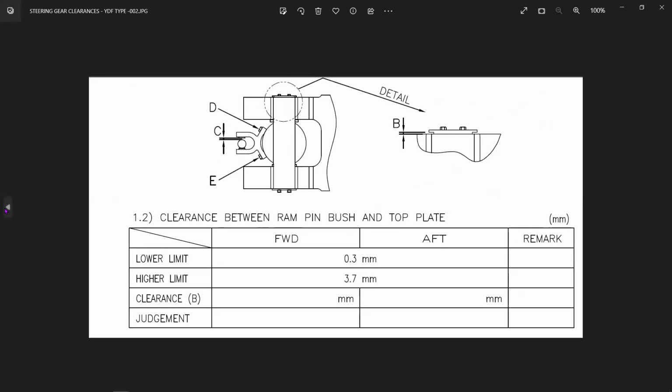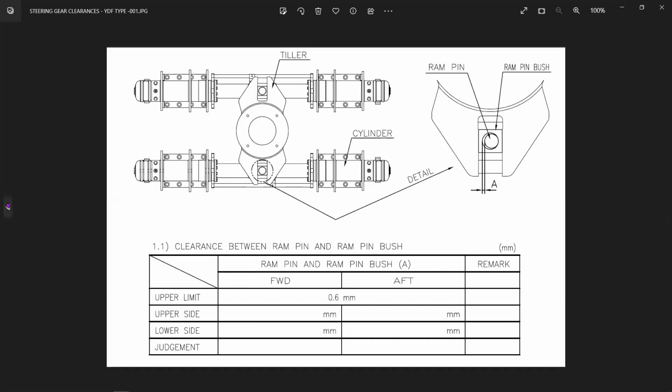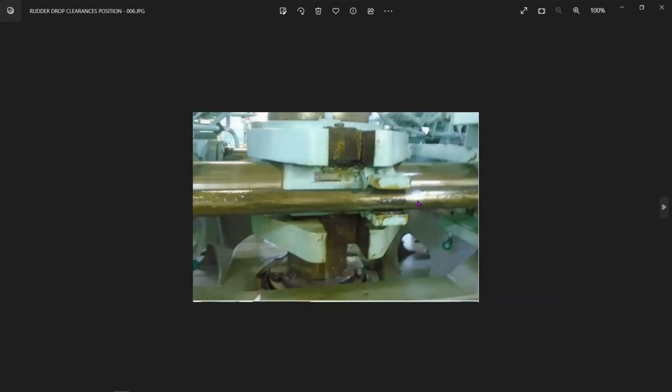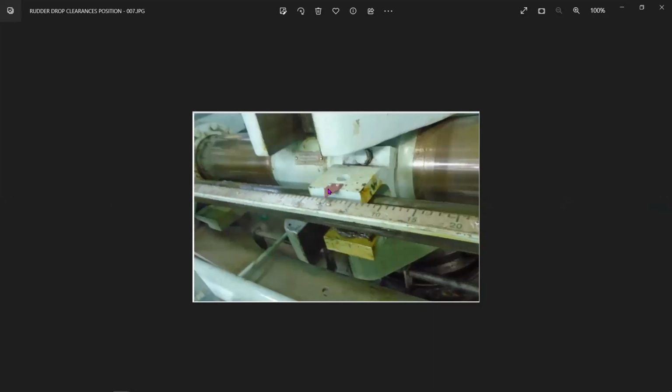Yeah, these ones. There is a guide rod, and this type of arrangement is acting like a rudder stop. Yeah, you see this? This is a rudder stop, and this will go in at maximum angle, say 35 degrees. It will go and hit the cross beam, which you have here across the two rudders, and it will not allow further movement. This serves as a rudder stop, and on the forward end you have the rudder indicator. Both sides have this movement, and there is again a separate guide beam which is just sliding on that. There is no pinning in this; it is just sliding over that.